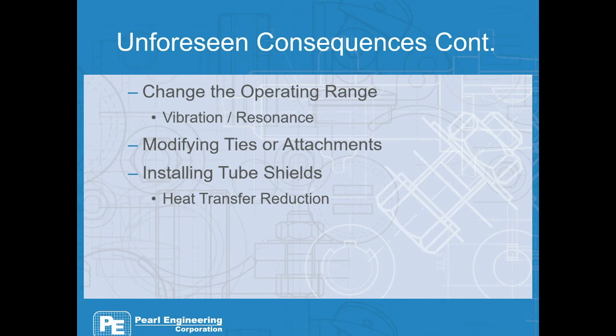You can have vibration and resonance in your backpass and in your breaching that could cause internal stiffeners to fail. It can cause a vibration that just makes excessive noise in your building. That can actually be found by hammer testing and acoustic monitoring inside during an outage, and you can help find what components internal are causing that vibration and resonance.